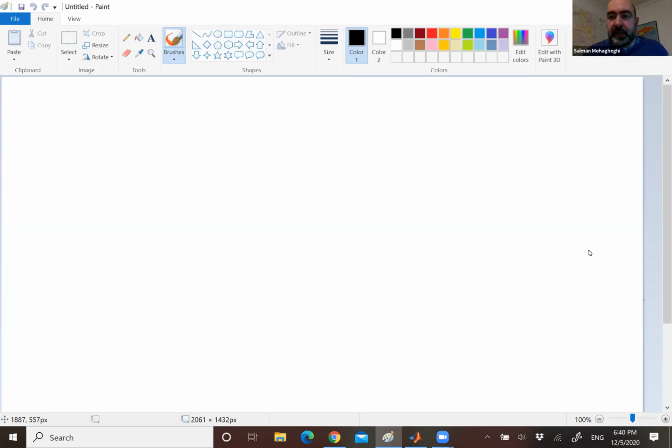Hi everyone. Today we'll talk about designing different controllers, P, PI, and PD using sisotool and in particular in the frequency domain. So let's do this through a couple of examples. Imagine I have a transfer function of the form G(s) = 10 divided by s times (s+2)(s+20). This is a third order transfer function, and this is my feed-forward path.